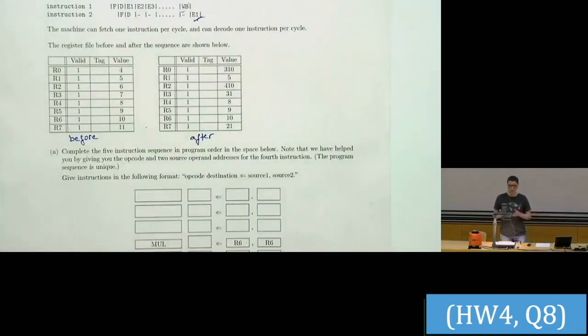Okay, so basically the decode operation here is allocating that entry, but when we talk about in-order processors, then decoding mostly means reading the values from the register file. And obviously you cannot read the values before writing the new values into there, right? Okay.